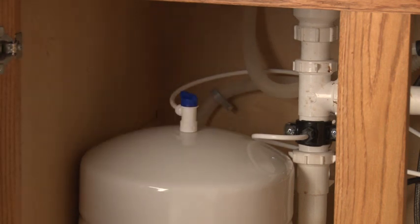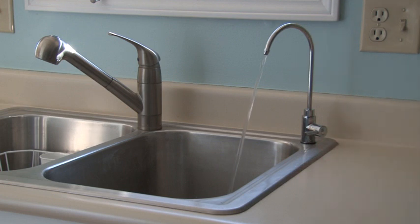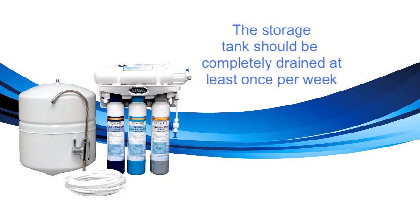After several hours, the storage tank will be full. Again, check for leaks. Open the faucet and drain the system completely. This will flush the carbon fines from the system. Shut the faucet. RO water will be available for use when the tank refills. The more RO water that is used, the better the water quality will be maintained. The storage tank should be completely drained at least once per week.